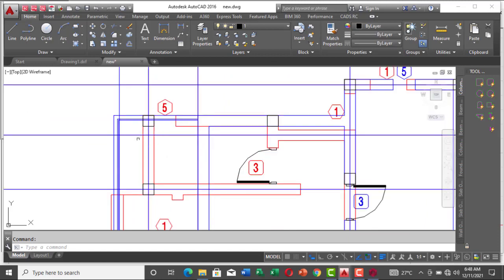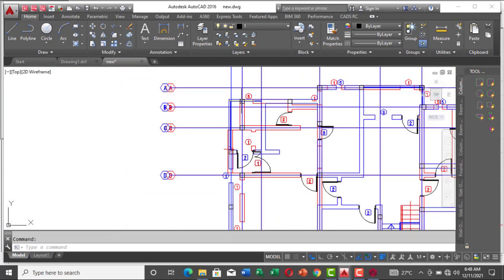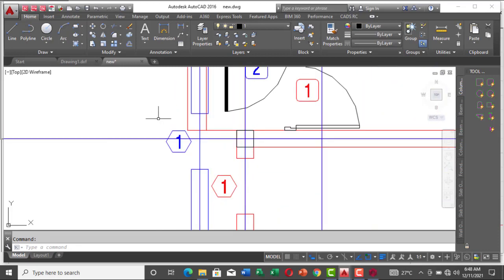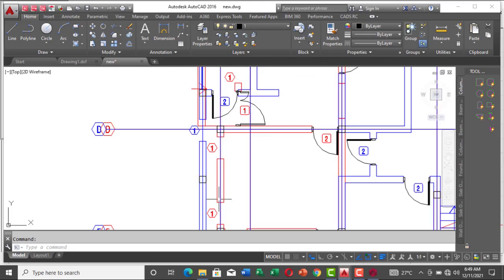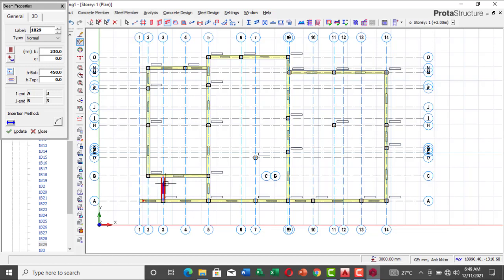All this portion here is going to be a cantilever on the ground floor. No, sorry, on the first floor. So when you stand on the ground floor, you'll be seeing this portion as a cantilever. So let me say I need a beam under here to carry the terrace. I also need a beam here to carry the terrace, and then part of this cantilever slab here. So I need a beam at this column, I need a beam at this column. I also need a beam at this column to protrude out, just a small beam. And then I think we are good. Okay, so let's take that too. So let's say I need a small beam here, just a small beam.